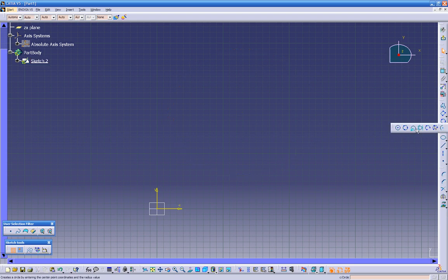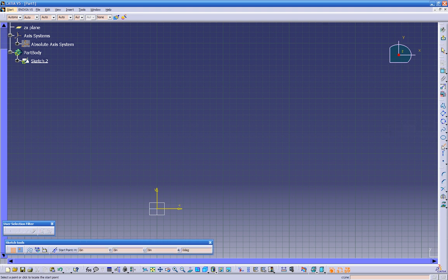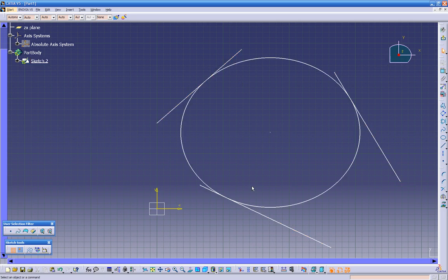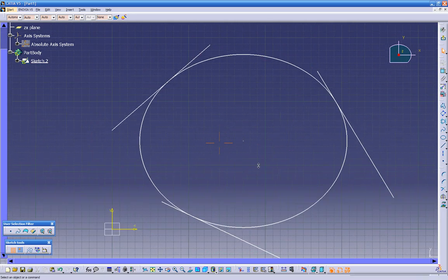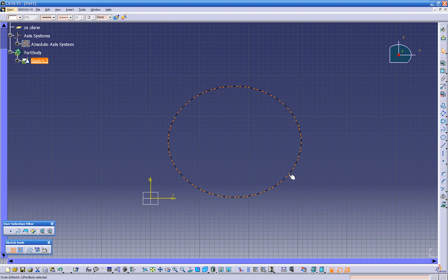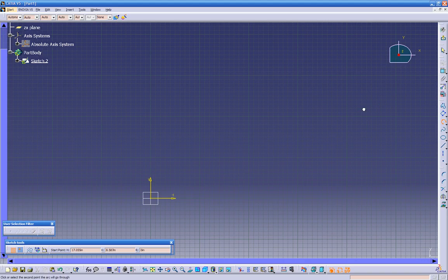Let's see what else. Coordinates, tangent with the 3 lines. So if we double click on the line, have a line here and a line here, we can click escape so we can get out of the line. Let's click on tangent, click on line number 1, 2, 3, and there's our circle. So let's delete this. We don't need this. Click on the circle and delete. So we have different options over here to create a circle, 3 points.